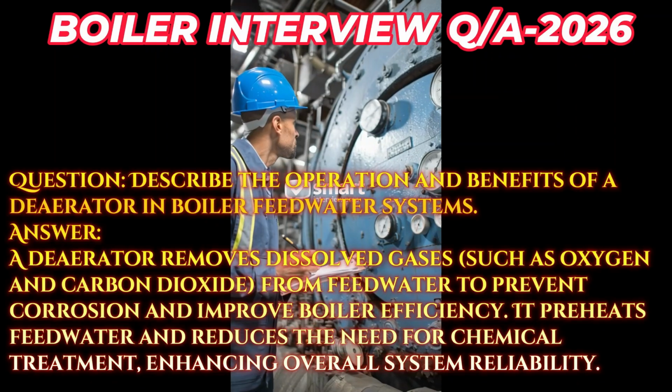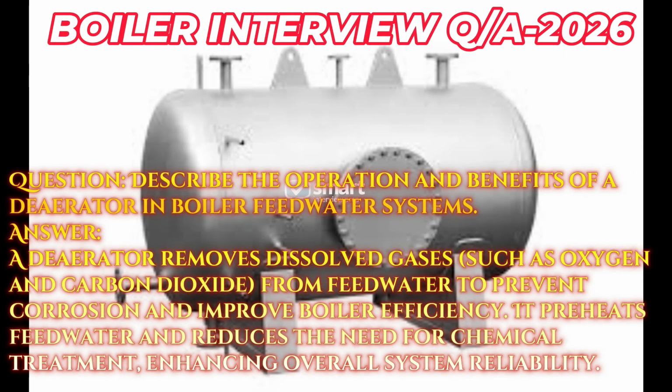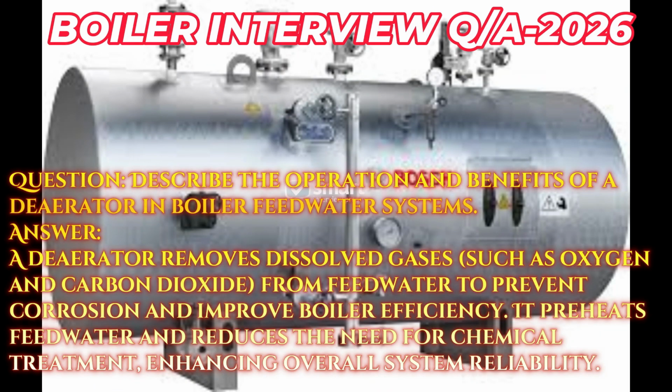Question: describe the operation and benefits of a deaerator in boiler feedwater systems. Answer: a deaerator removes dissolved gases, such as oxygen and carbon dioxide, from feedwater to prevent corrosion and improve boiler efficiency. It preheats feedwater and reduces the need for chemical treatment, enhancing overall system reliability.